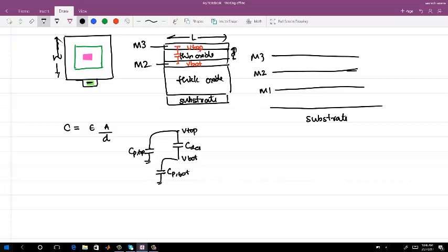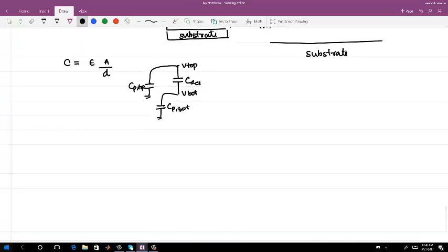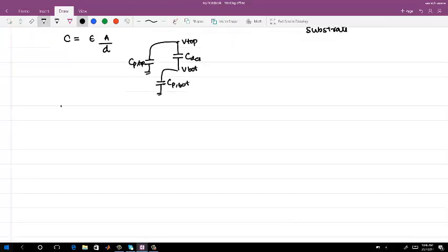Okay. So now if you are realizing a loop filter which captures C desired, you also check out what are the other things which are coming in addition to it. Now the other capacitance, this is the parallel plate capacitance, is which you can realize using the fringe capacitance.